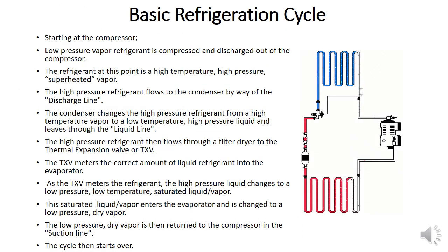In this basic representation of the refrigeration cycle, the compressor is the starting point. On any PV and TS diagram, the starting point is the compressor, known as starting point 1. The compressor is represented in that diagram on the extreme right side. One motor type of device is shown. So when we start the basic refrigeration cycle at the compressor, low pressure vapor refrigerant is compressed in the compressor. It is a hermetically sealed reciprocating type of compressor, which is generally used in household refrigerators and air conditioners.